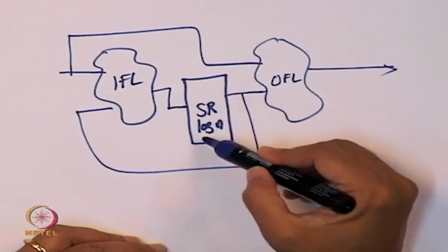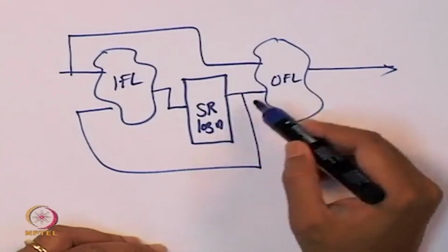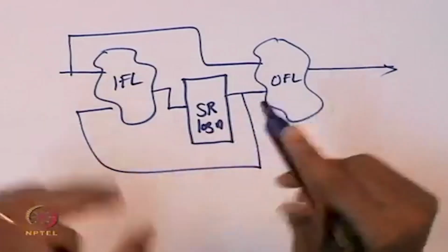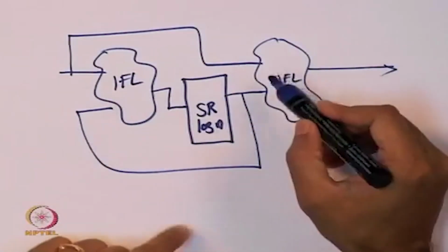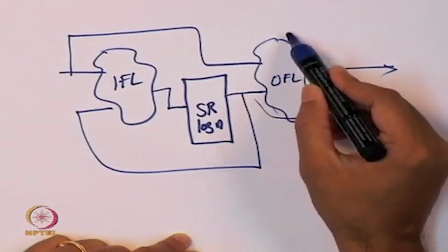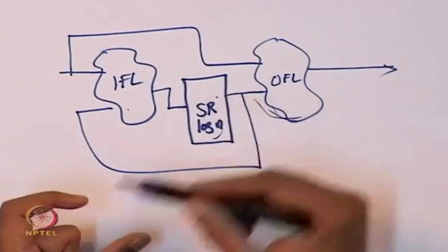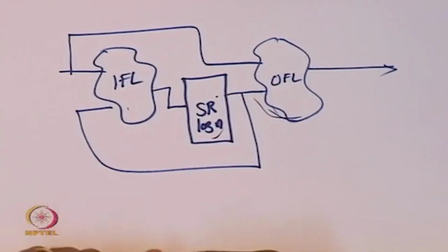Because you have encoded it densely, when you have to do things like, for this state the output must be 1 and so on, technically you are actually decoding it within this circuit. You decode here and you decode here because you have encoded the states here. Whereas when you do this in one hot encoding, you actually do not do that. So there is something nice that happens in one hot encoding.